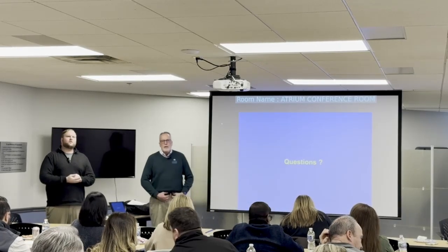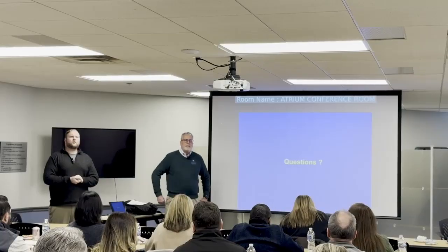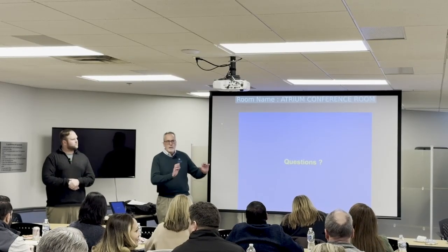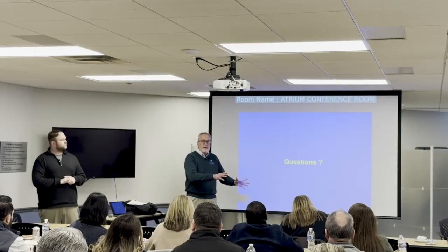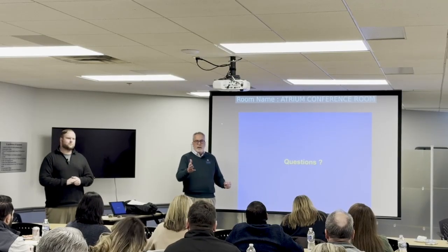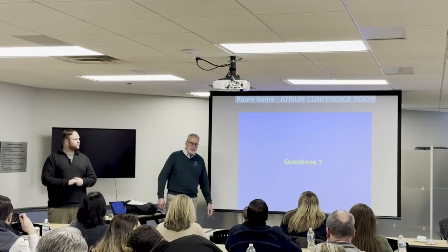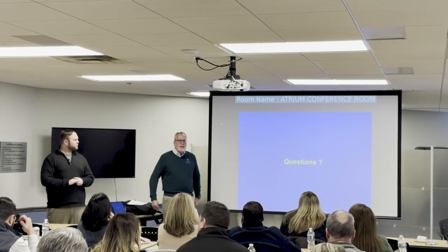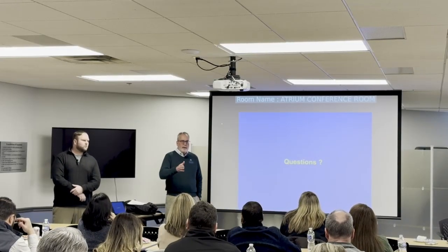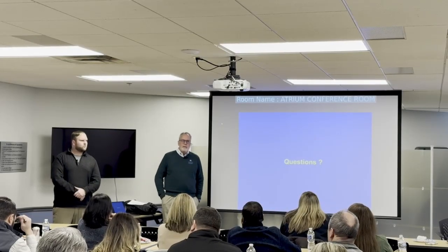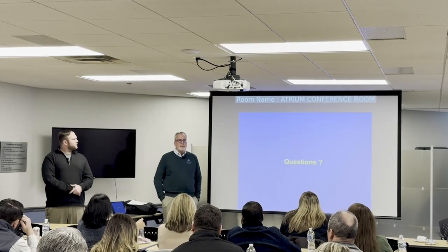So it would be your recommendation to do a phase 1 and then do the phase 2? Yeah. If we come out and you say there was a tank here, we do a couple borings, we'll say, hey, that was clean. But it doesn't tell you if there's other impacts to the real estate. We really need to know the history of the site, the history of the adjacent properties, and really get down to the point where we know that's the only issue we've identified. And then you know, that would be the appropriate way to do it.